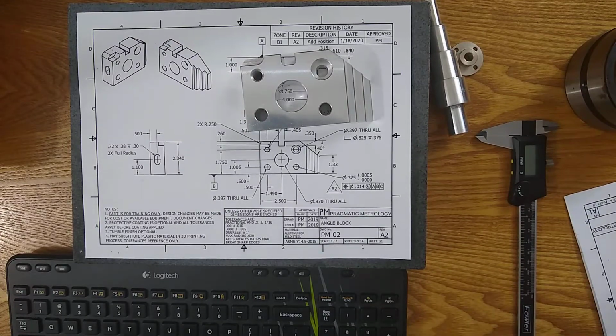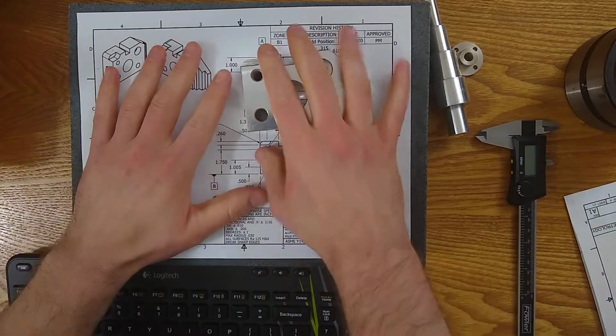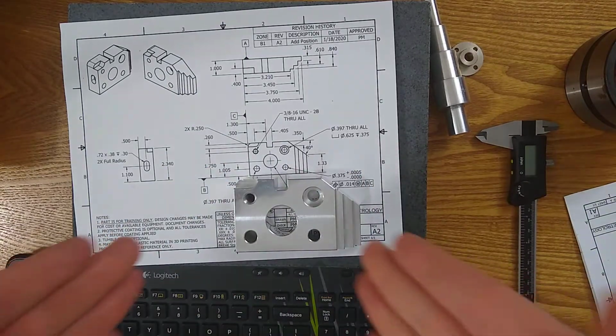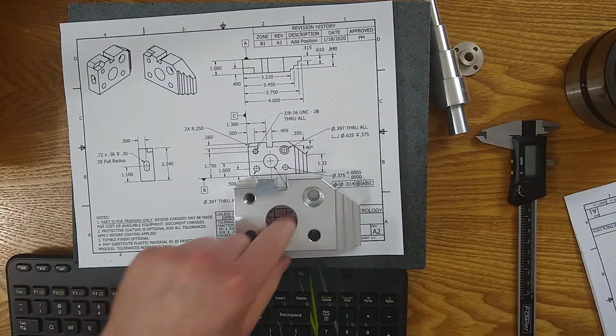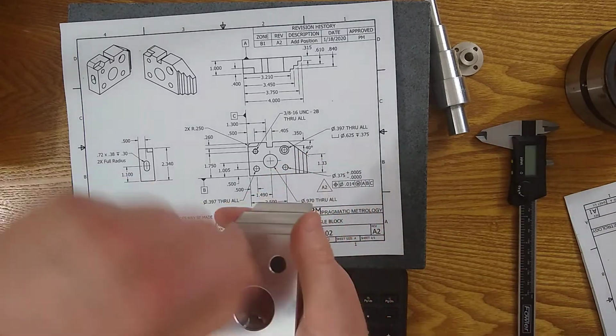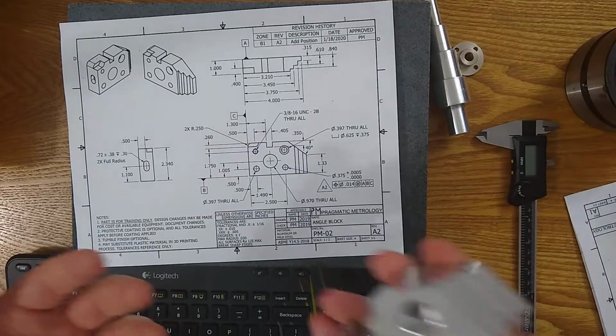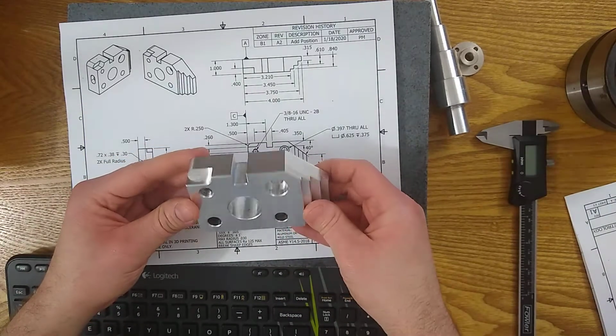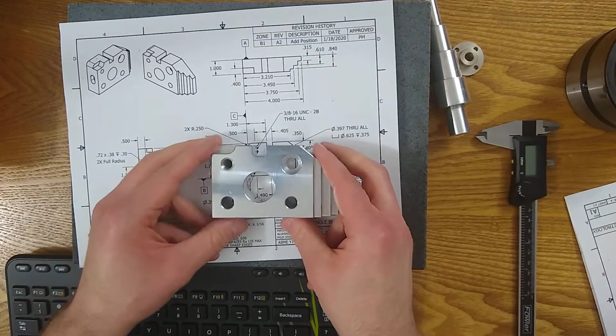Precision holes. So holes with a tightly controlled diameter tolerance. Here's the list. You could do it with a reamer, an end mill, or a boring bar. What you want to look for that won't necessarily be on the prints is taper. As I mentioned, the holes can taper, or the diameters can taper. You want to look for good surface finish on a tightly controlled diameter, because if it's really rough, you might still get a gauge in there and get a measurement, but you're registering on the high points and not picking up all the low points, and that may not be good enough. So you want a good surface finish with no chatter. You want to check for form error.